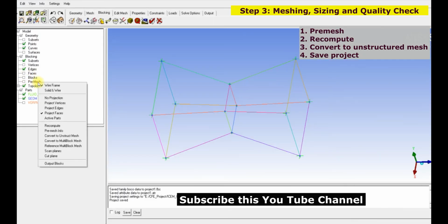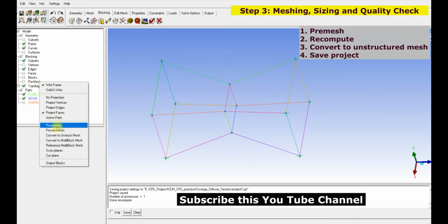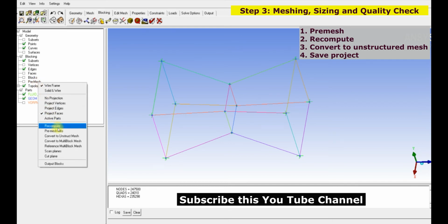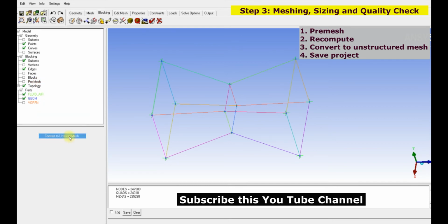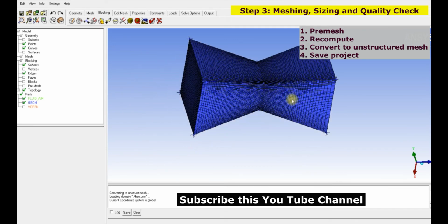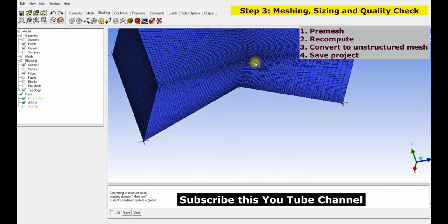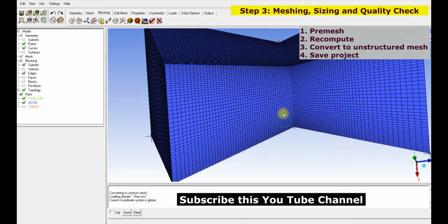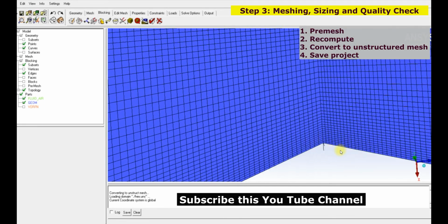Then here click recompute. Then you can also show the pre-mesh information. That means how much mesh size will be created here. That means 2,35,000 mesh will be created. Then convert to the unstructured mesh. This way the structured mesh is created. We get uniform variation in mesh size.